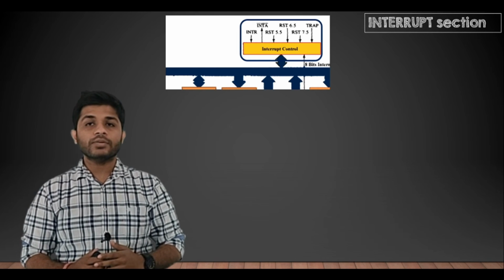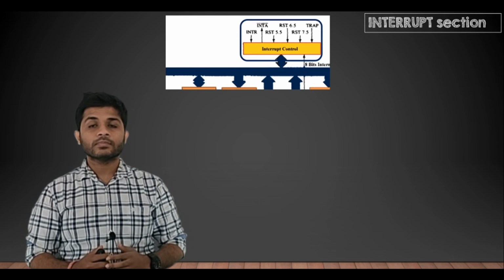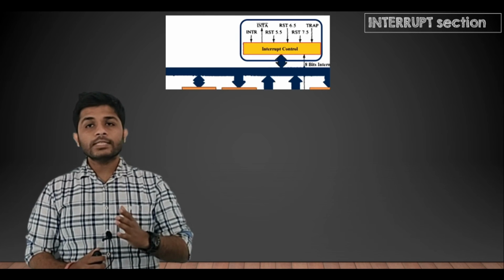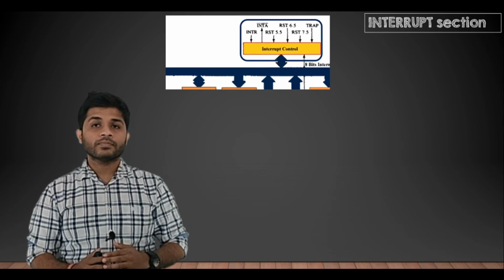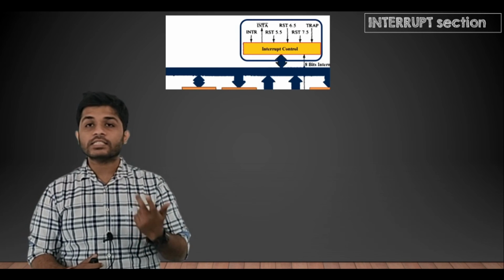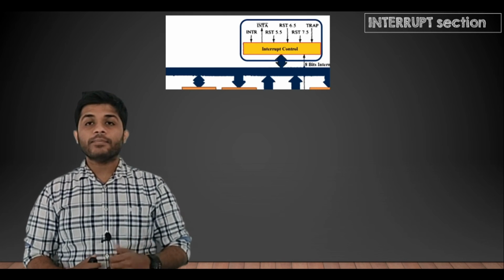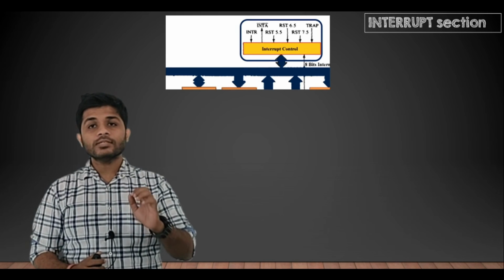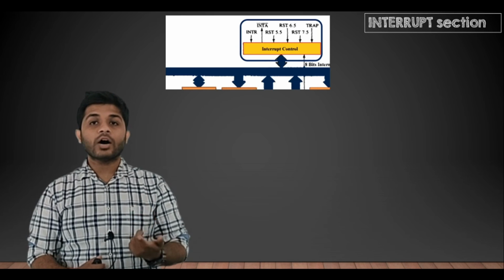Generally, interrupts are divided into two types, hardware interrupt and software interrupt. Right now you can see in the block diagram it is the hardware interrupt. You can see in the interrupt section there are 6 pins. There are TRAP, RST 7.5, RST 6.5, RST 5.5, INTR and INTA bar. So you can notice that from these 6 pins, 5 pins are input and 1 pin is output.